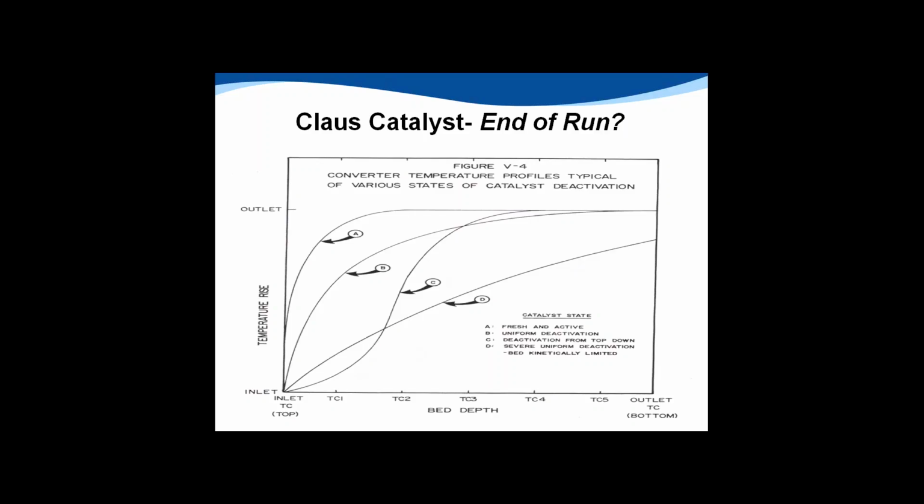By understanding and always assessing our temperature profiles from the DCS, our operating team can have a good idea in their mind in terms of, one, are we achieving the recommended converter operating temperatures? And also, where in the bed, at what depth, are we achieving that maximum temperature or equilibrium temperature? These profiles will change with time, with natural aging. All that information together can paint a very clear picture in terms of overall catalyst quality, or when we should maybe consider replacing the catalyst in our beds.